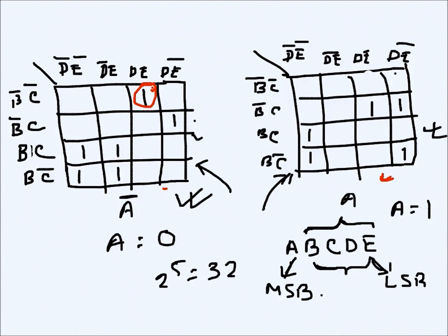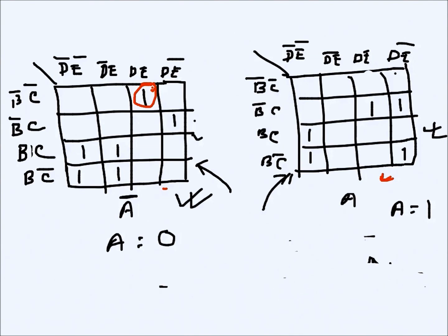Okay, so this one goes by itself, and I will write the expressions here. Since this one is just by itself, the expression is A bar, it will stay there, and this square is B bar, C bar and D, E. So all 5 variables come here because this is just by itself. Looking at this one, I can group this one with this one.